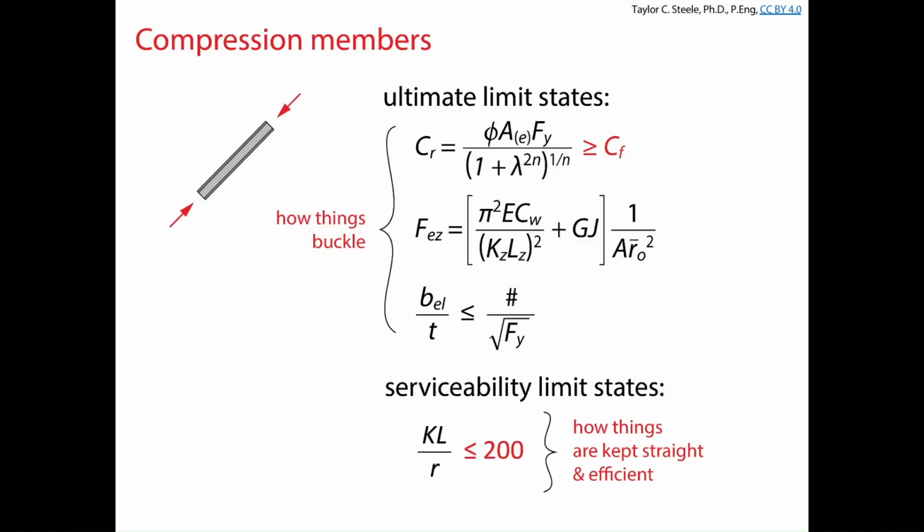So we talked about designing tension members quite a while ago. We tried to back calculate the area that would be required, right? So we looked at gross section yielding. We looked at estimating the net section in terms of the area removed for bolt holes if we're bolting, and the shear lag effect. And what we could do is basically back calculate the effective area or the total area in the section we need to satisfy the tension limit states.